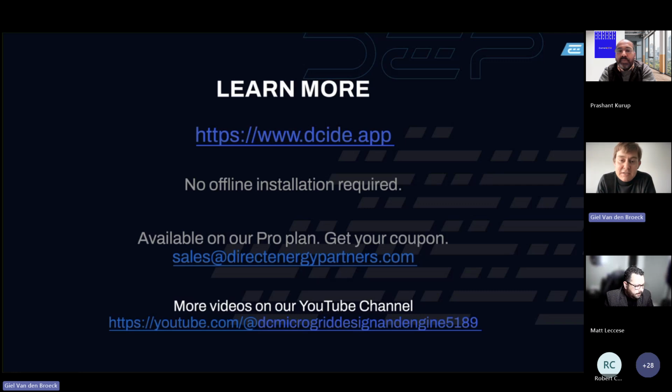Go there, design a diagram, run a power flow simulation. That's something that I didn't cover in this presentation, but one in the past. You can, for instance, do efficiency analysis, specify the conversion efficiency of a power converter, and evaluate the losses overall. You can upload load profiles as well in here and check how voltages and currents propagate in the network.